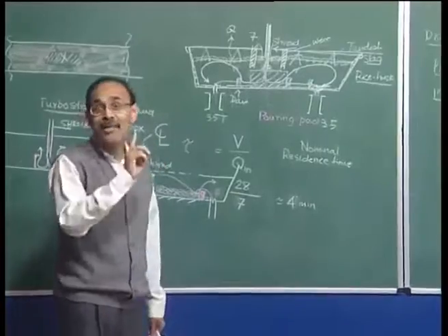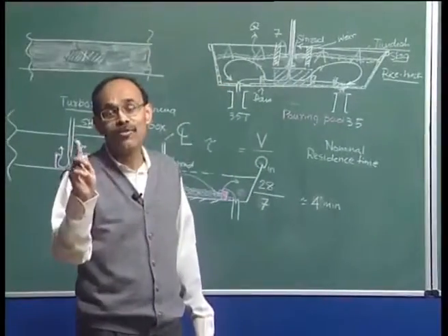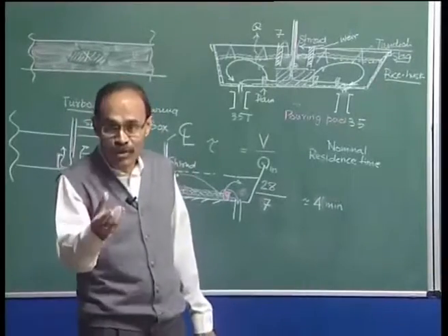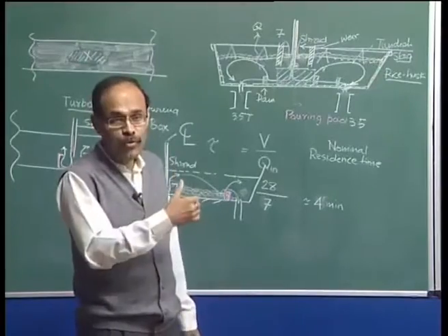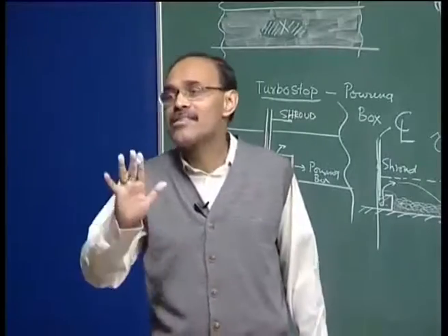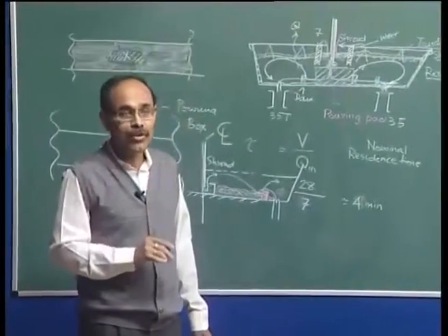On the other hand, if you want to separate out or remove inclusions, we do not want that high mixing flow, we require what is known as a plug flow, or a very weak kind of flow which will be conducive to inclusion flotation. Indeed, if you have plug flow and surface directed flow, that tundish is ideal as far as removal of inclusion is concerned.